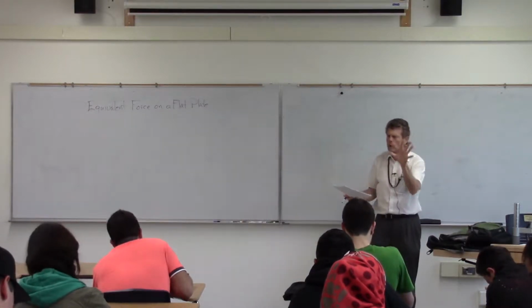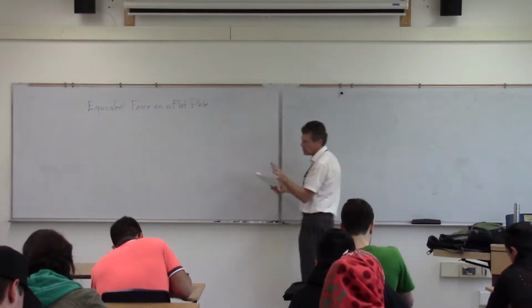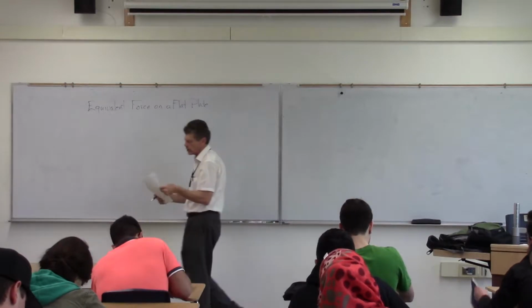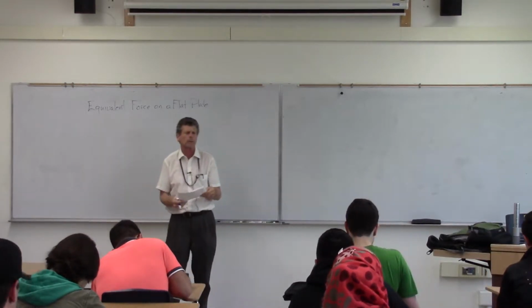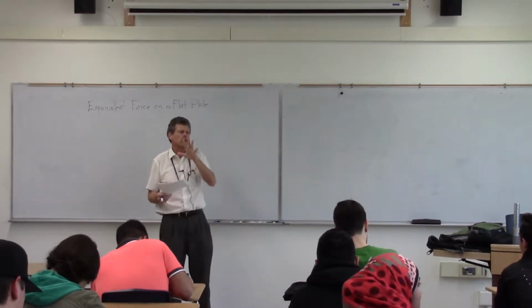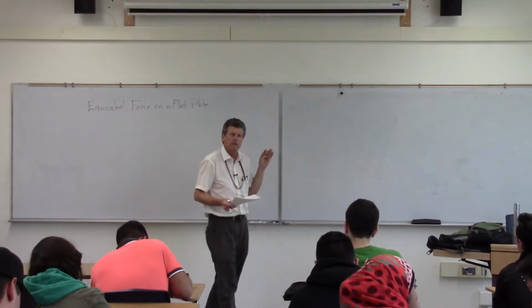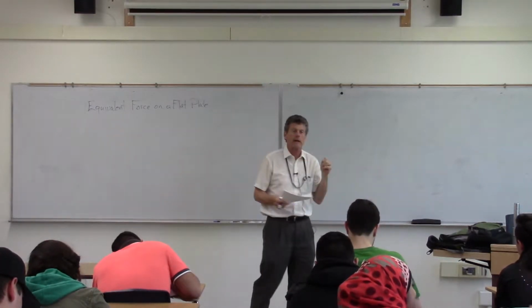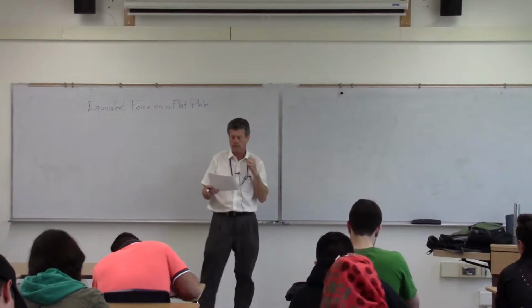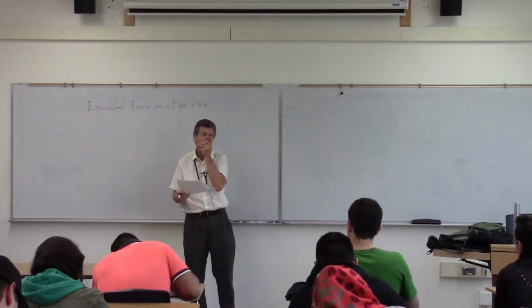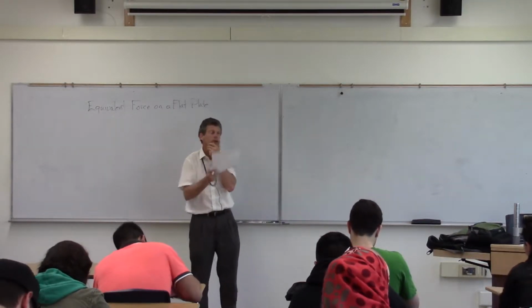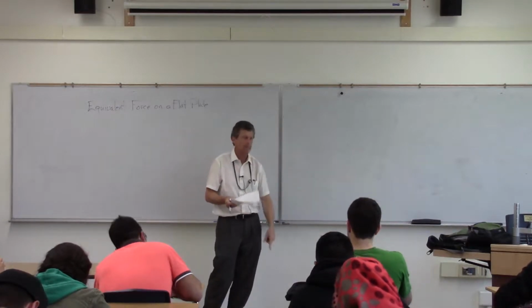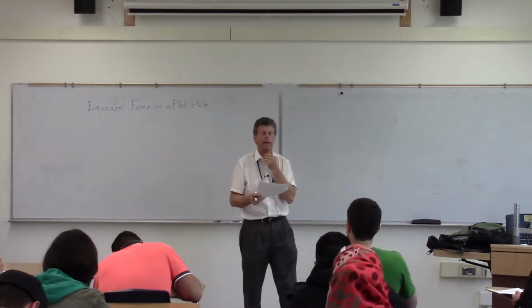Okay, so what we're doing with fluid forces, remember we talked about fluids and all those characteristics. So what were some of the characteristics we talked about? What were some of the unique things about a fluid force? Perpendicular, it acts perpendicular to the surface. Linear increasing with depth. And it acts on an area.